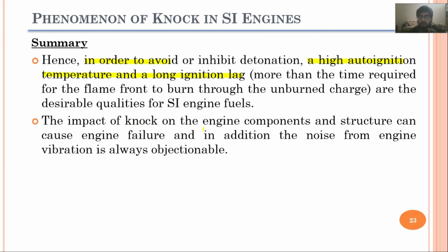The impact of knocking on the engine components and structure can cause engine failure, and in addition the noise from the engine vibration is also very objectionable. So we have to ensure that we do not have any knocking in our SI engines, and we can avoid that by utilizing a good quality fuel which has a higher auto ignition temperature, or a long ignition lag.